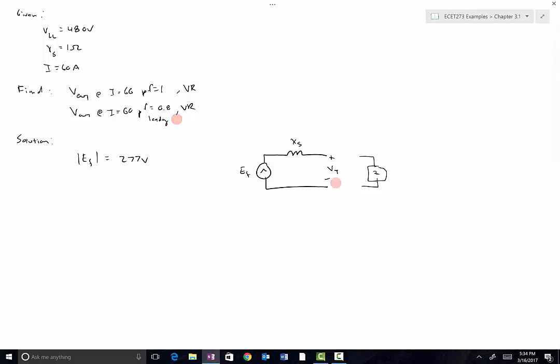So big picture, what's going to happen is the magnitude of the terminal voltage is going to change, and the angle of the excitation voltage is going to change. Magnitude of excitation voltage, though, is set by the excitation current, and it's fixed unless somebody adjusts it. So we're analyzing the condition on what happens before somebody adjusts it.